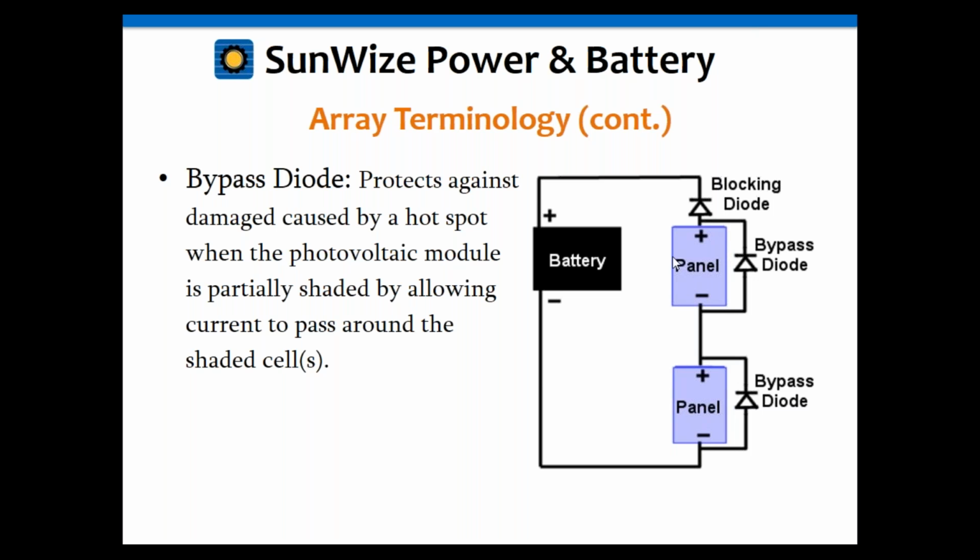Okay, but you will notice here that the diode, again, there's a blocking diode we talked about earlier, and they're really not used too much anymore. This is pretty much integrated into the charge controllers nowadays. But with the bypass diode, you'll notice that the line on it, the blocking end of it, is up here at the plus. So what happens is the current's pretty much flowing out of the module, through the battery, and back this way through the array.